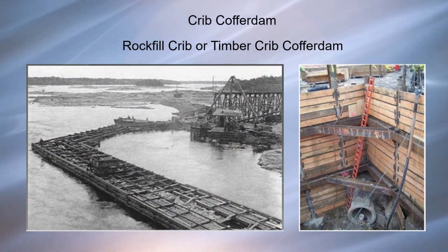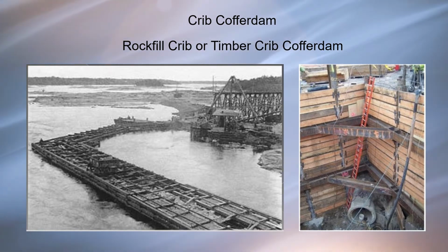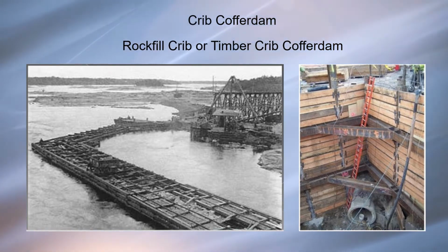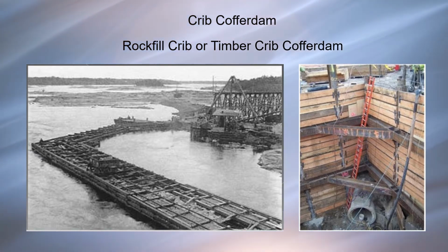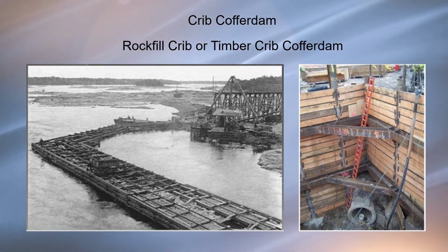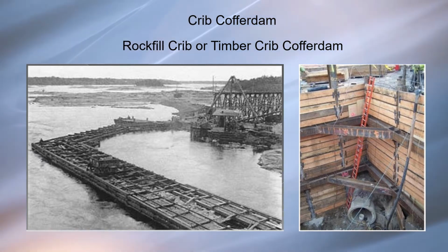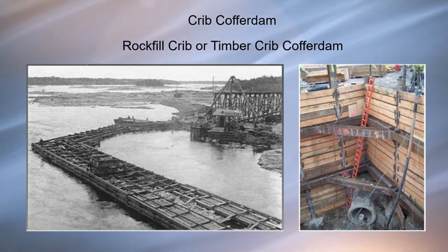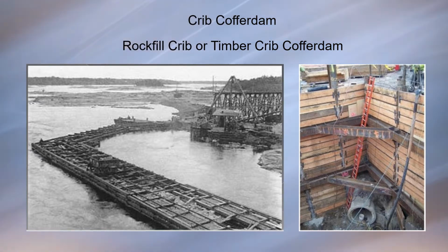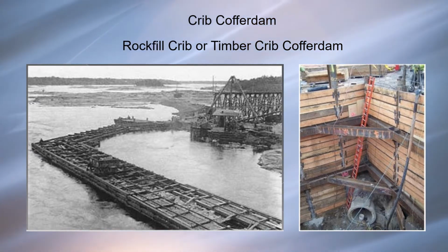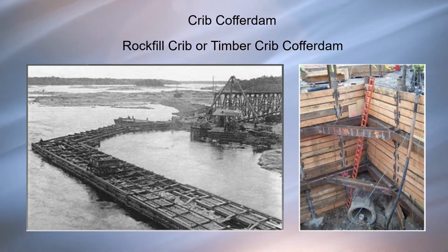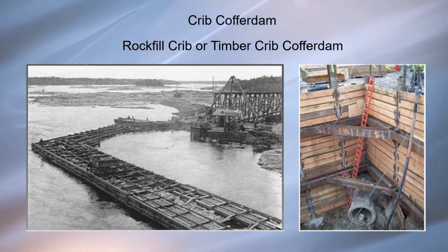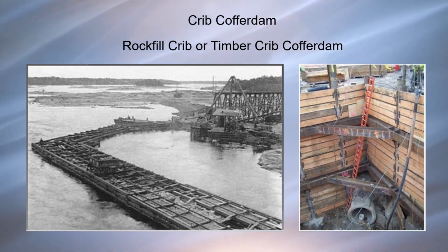Creep cofferdam. If the stream has a hard bottom, it is difficult to penetrate the guide piles or sheet piles. In such cases, a creep cofferdam is used. It is suitable when the depth of water is in the range of 10 to 20 meters. It is used for wide excavation and rocky river bottoms.